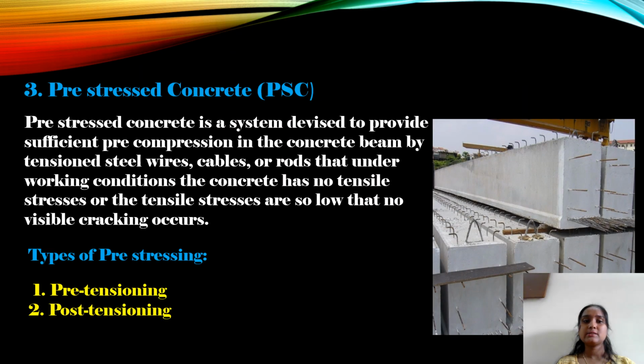The last one is pre-stressed concrete, also known as PSC. Pre-stressed concrete is a system devised to provide sufficient pre-compression in the concrete beam by tensioned steel wires, cables or rods, so that under working conditions the concrete has no tensile stresses, or they are so low that no visible cracking occurs. This can be divided into two types: pre-tensioning and post-tensioning.